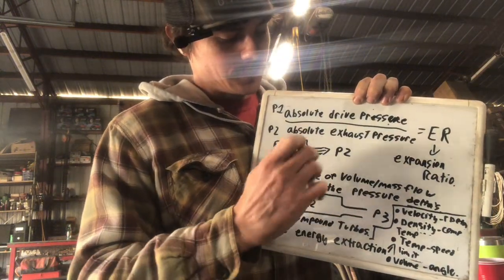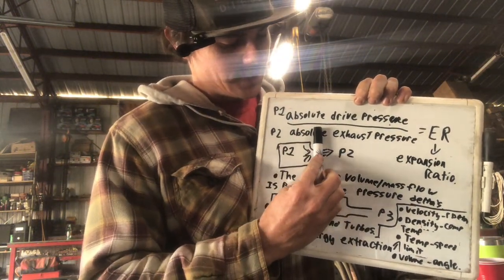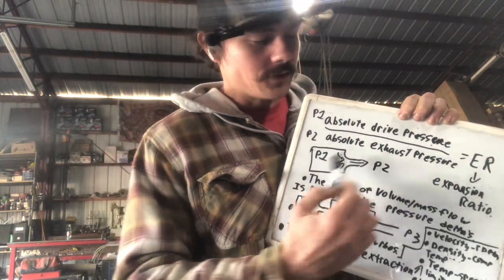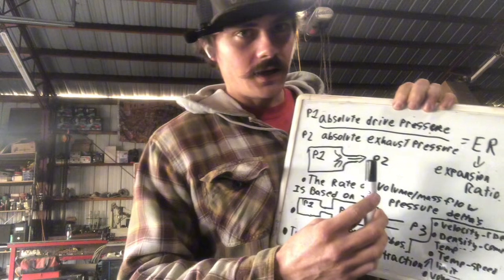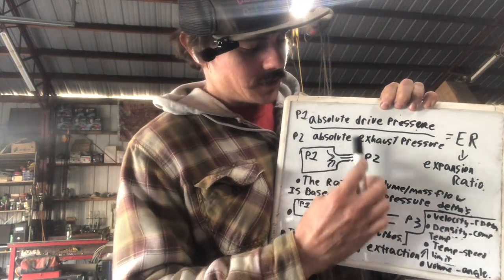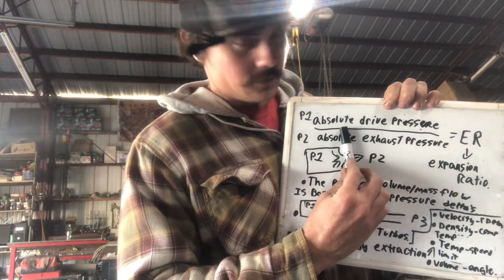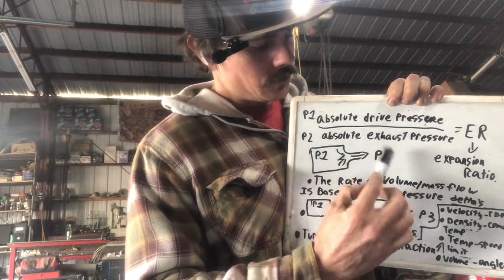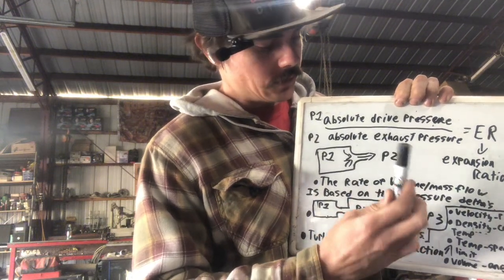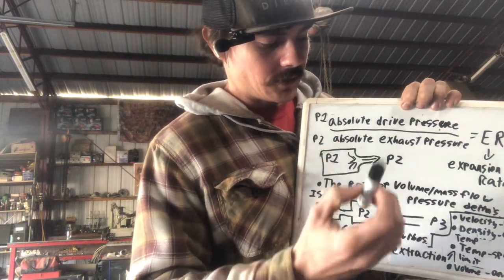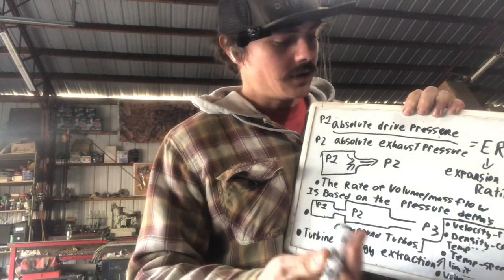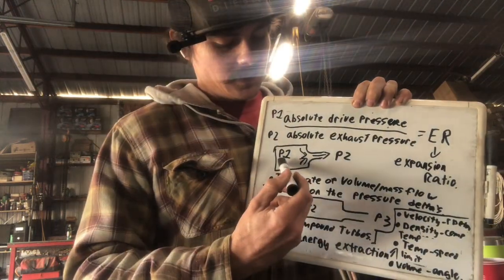This becomes an air compressor, right? You have essentially cut this off, and as the motor runs, the pressure in here would rise. And because pressure rises, now it starts to flow, right? But if you could make sure your exhaust pressure was always the same as drive pressure, you would cut open this channel to atmosphere, and P1 would always match P2. As the motor continued to run, pressure would continue to go up because the motor is pumping the exhaust gas into a tank, essentially, and it will just continue to go up.